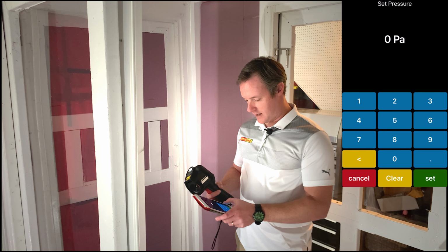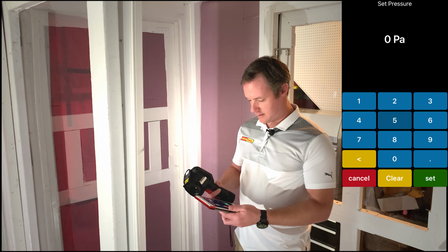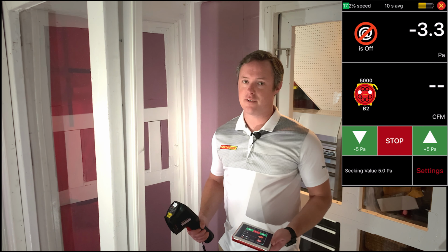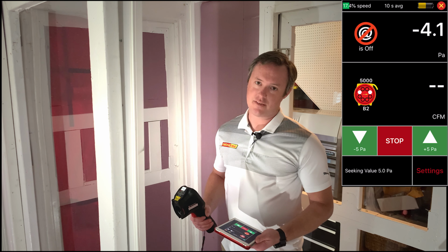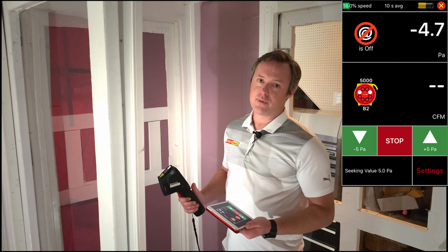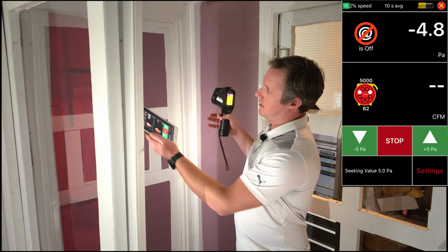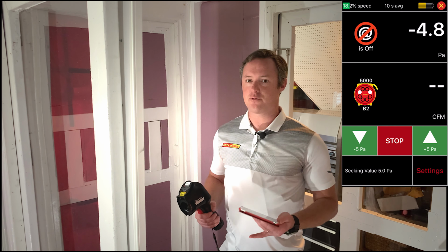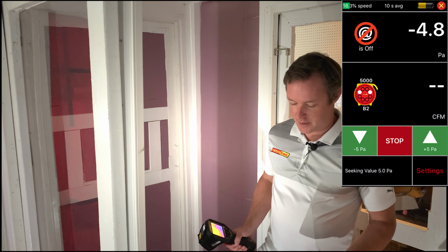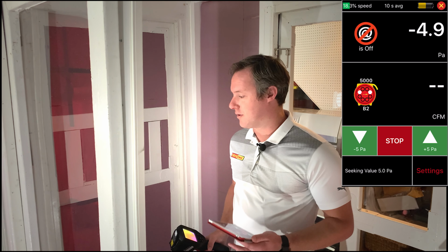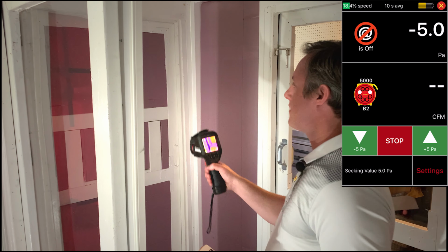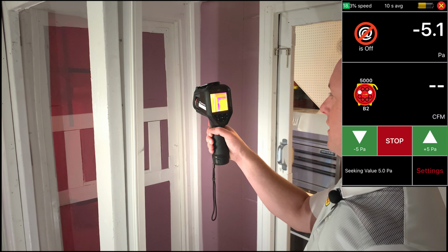So now we'll set to 5. And one thing that I did here was I flipped the fan around so that we're depressurizing the space. That way we're exaggerating those leaks across the envelope and bringing that air inward. That way we will see that cooler outdoor air come in on our thermal camera. So we've achieved that -5 pascal pressure differential. It's been running for just a little bit now. So let's take a look with our camera and see what we have here.